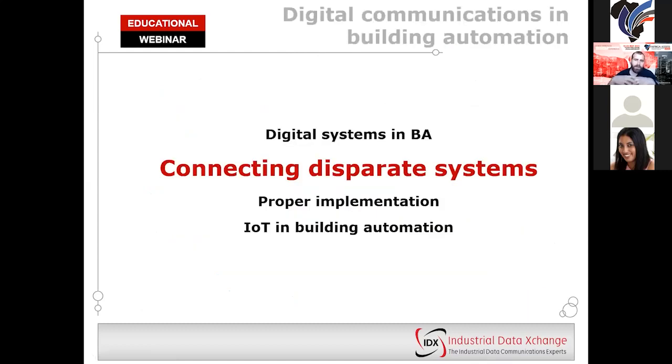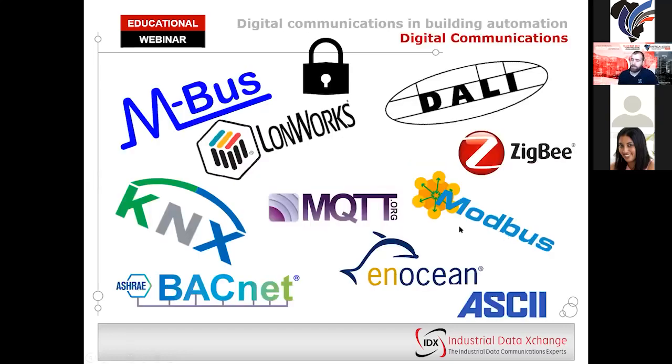Now, we already understand the challenge with proprietary protocols not being able to communicate between the various different manufacturers. But what happens when you want to interlink devices that talk different standard languages, such as, for example, a Modbus power meter, which I've been referring to, and maybe a KNX building controller. I have a KNX controller that can do something smart with the power usage from that.